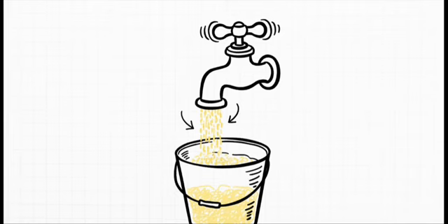Even though the water is only ever coming out at full pressure, because it's only on for half the time, the bucket is going to fill up at half the speed. You're controlling the average flow by controlling the ratio of on time to off time. That is exactly what PWM is doing with electrons.